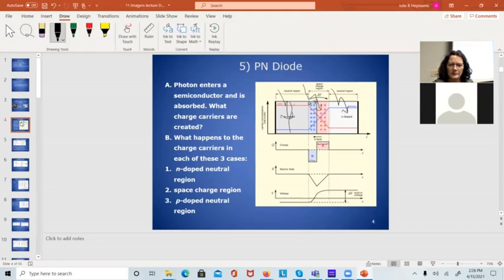We usually dope them to have a large depletion region on the inside and a smaller depletion region on the P side. And then as the photon comes in, it absorbs an electron with its hole, and you slowly discharge the capacitor. So the capacitance of the PN junction diode. I gotta stop calling it a capacitor.